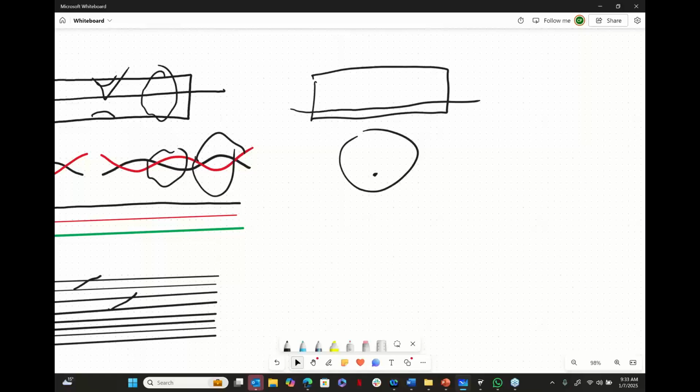Why? Because even though this is clearly no longer a 75 ohm environment and this cable is seriously jacked up, a TDR still sees this as a constant impedance all the way through. It's not unlike looking down a railroad track and comparing one side to the other and it's saying, yeah, that's perfectly straight to me. It's got no idea if it's supposed to be this wide or this wide. It is still a constant impedance. Everything else still applies, right? Kinks in the cable, water in the cable, impedance mismatches between it.